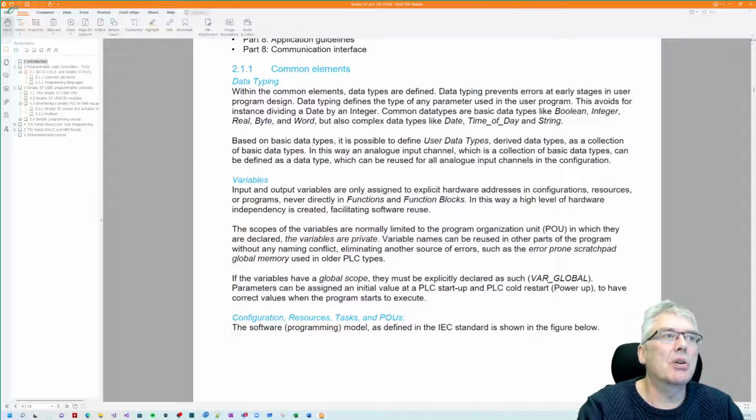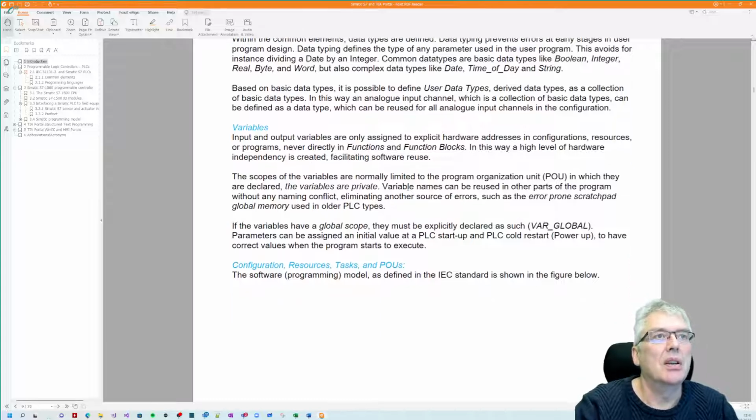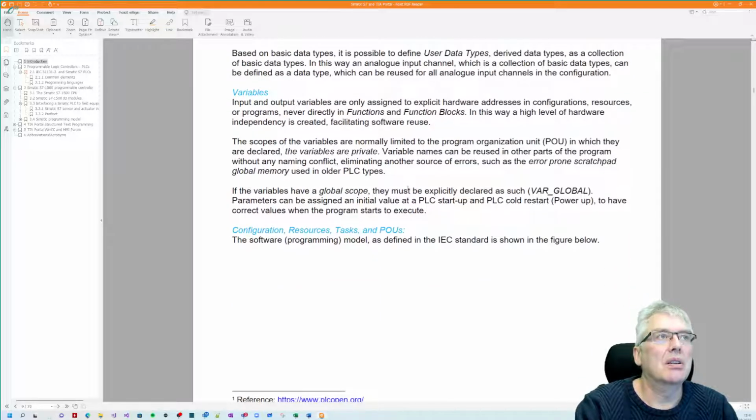So when it comes to programming, we have got data types that we are programming on. PLCs are binary machines a lot. Programmable logic controller, true, false. They are Boolean data types. But modern PLCs are computers. They are capable computers, so they can work on floating point, which are real, and complex data types. So they can do quite a bit of this.